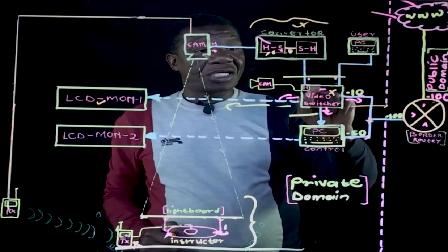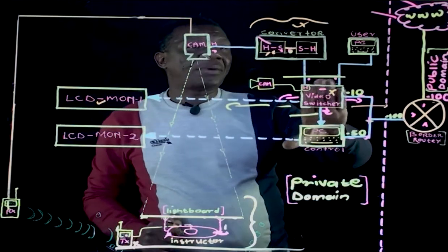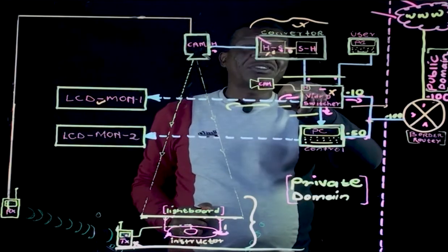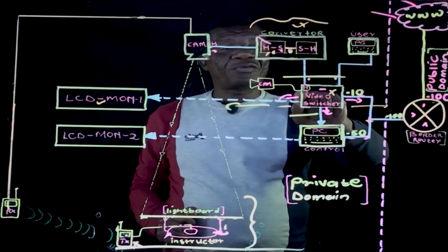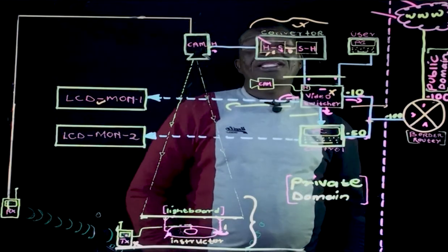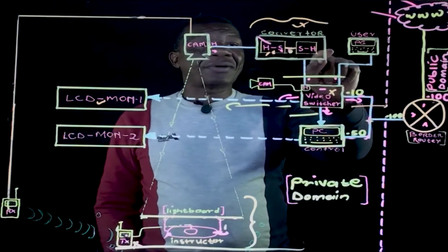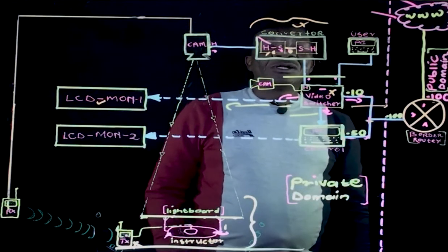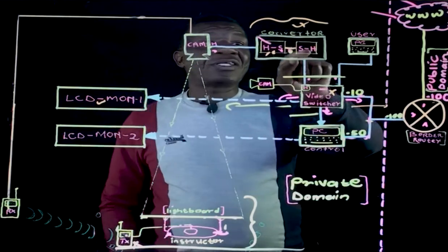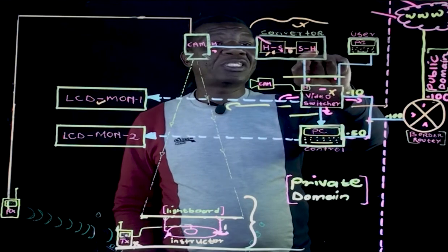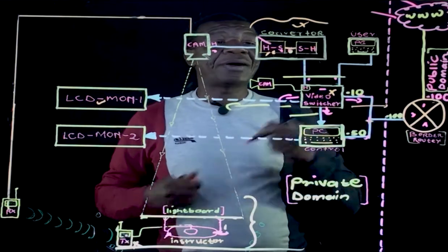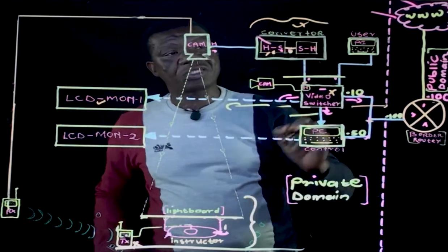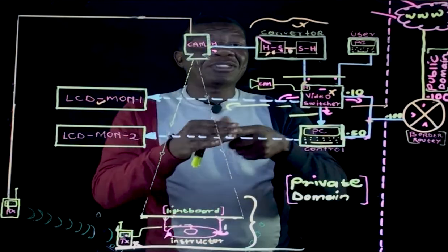Now I said the video switcher has got only an HDMI port. So this converter is giving us SDI output, which is not going to fit into an HDMI port. So we again need to convert SDI to HDMI so that we can output HDMI to the video switcher's HDMI port. So we have to get a second converter that is converting SDI to HDMI. Then we send the HDMI to the video switcher. So now everything has landed in the video switcher. Everything from the camera is now sitting in the video switcher.